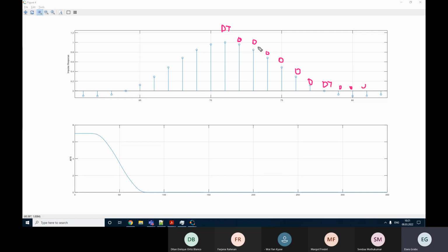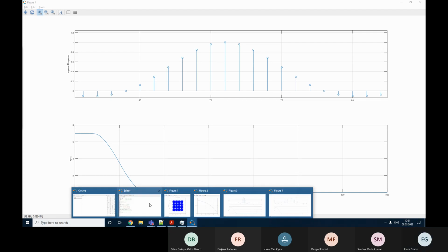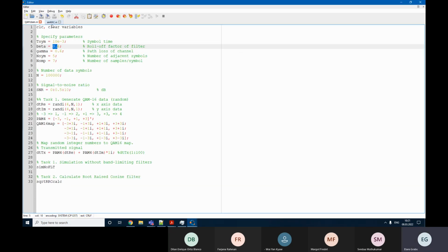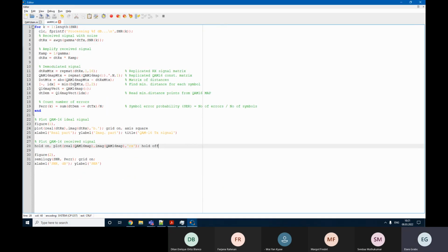So once per 7 samples, we send one data sample and accordingly 7 minus 1, 6 zeros, right? So we need to introduce these zeros first before filtering. Otherwise, we will distort our signal irreversibly and we'll lose data.